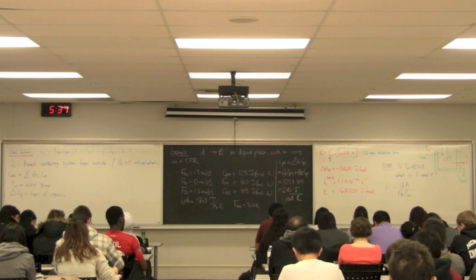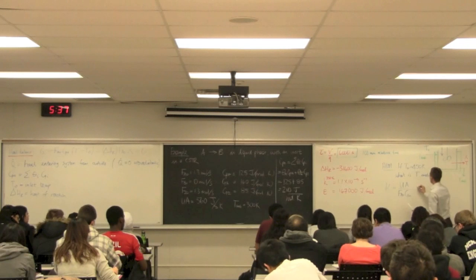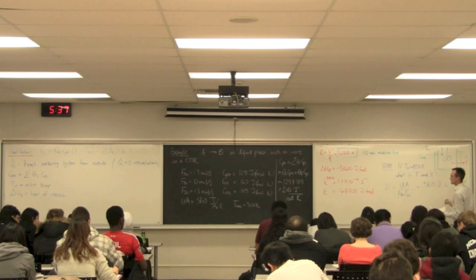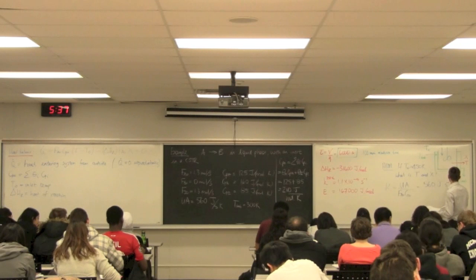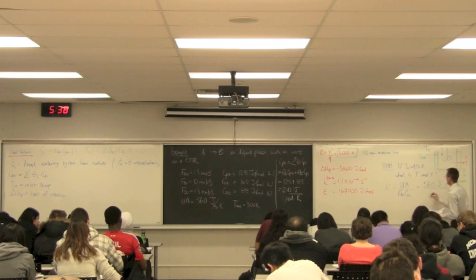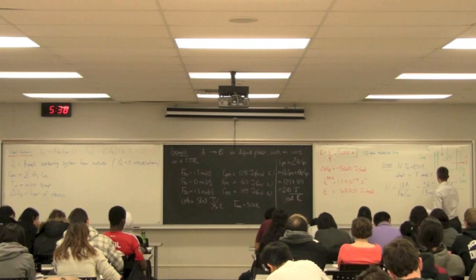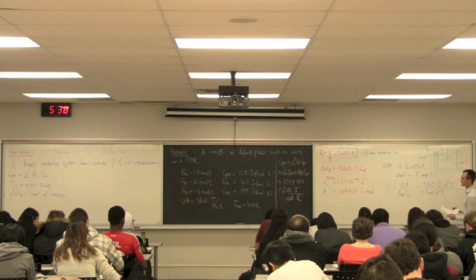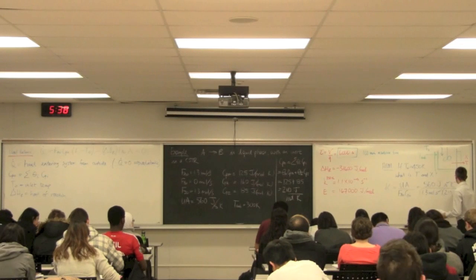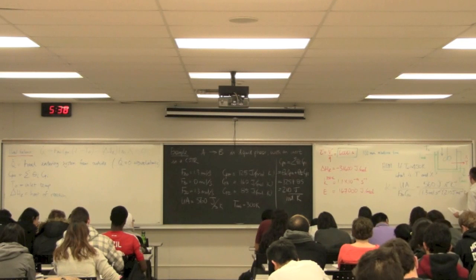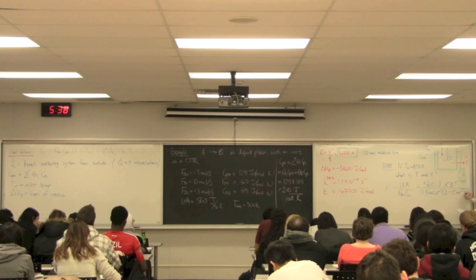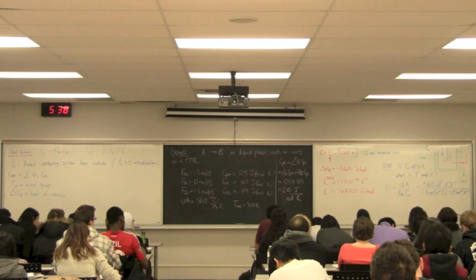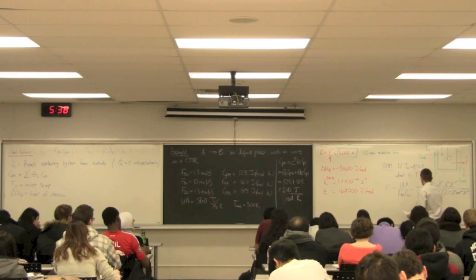So when we calculate kappa, yesterday we had that that's equal to the product of U times A, which we were told was 560 joules per second per Kelvin, divided by F_A0, 1.3 moles per second, multiplied by C_P0, which is 210 joules per mole Kelvin. So units cancel there, joules cancel, moles cancel, and I get a dimensionless number of 2.05.